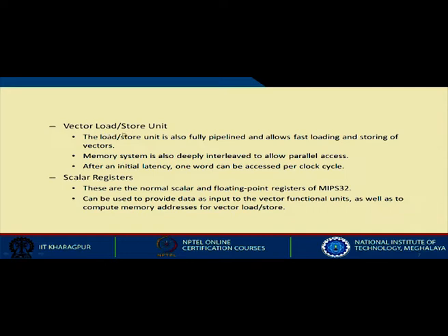Regarding the vector load store unit, as I said, that is also fully pipelined, and it allows fast loading and storing of the vectors. To allow this, the memory system has to be very deeply interleaved. So, 2-way or 4-way interleaving will not do; maybe it will be 16-way or 32-way or 64-way interleaved.